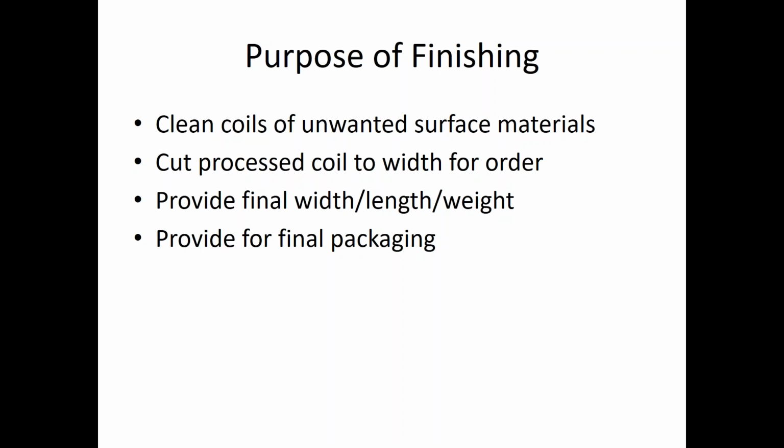During rolling, you have rolling lubricants, usually a water-soluble oil, that has to be taken off in many cases because of the different oil than what you want to put on if you're packaging it with a special preservative. They can clash. And you want to make sure it doesn't have any oxides on it or anything like that.